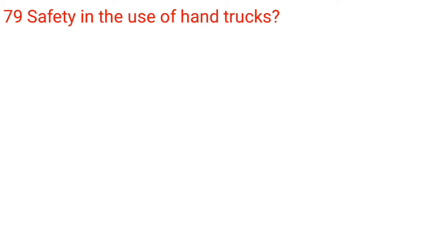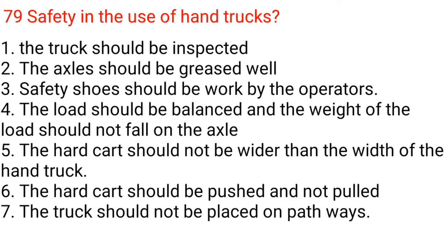79. Safety in the use of hand trucks. 1. The truck should be inspected. 2. The axles should be greased well. 3. Safety shoes should be worn by the operators. 4. The load should be balanced and the weight of the load should not fall on the axle. 5. The hand cart should not be wider than the width of the hand truck. 6. The hand cart should be pushed and not pulled. 7. The truck should not be placed on pathways.